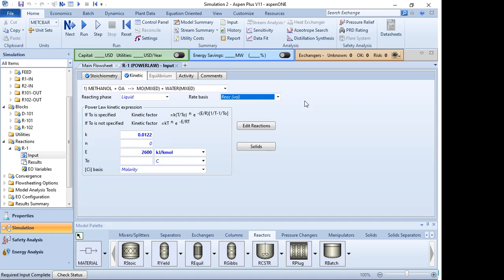physically it looks like a plug flow reactor, but inside the reactor you fill it with some amount of catalyst, so that the reaction is not only based on the length of the reactor, but it is based on the weight of the catalyst, based on the volume of the reactor.